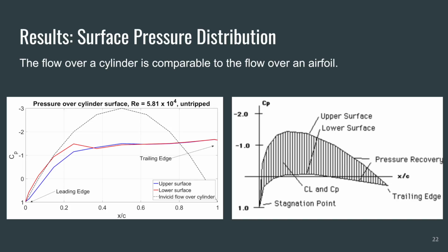The pressure distribution on a surface can say a lot about its aerodynamic performance. The area between the two curves is the two-dimensional lift coefficient. The y-axis is inverted so that for the airfoil, the upper surface with a lower pressure will also be the upper curve. This is not true for the cylinder measured, which indicates a small downward force on the cylinder caused by the vortices in the wake causing downwash on the cylinder itself.